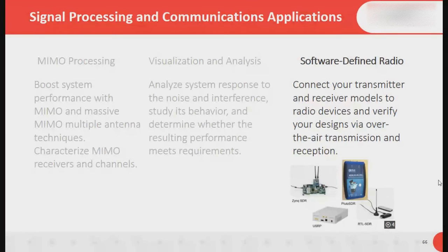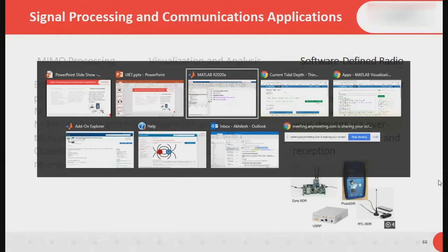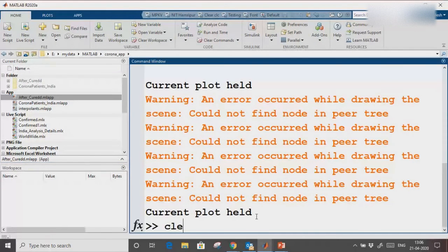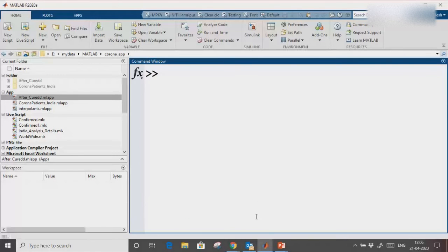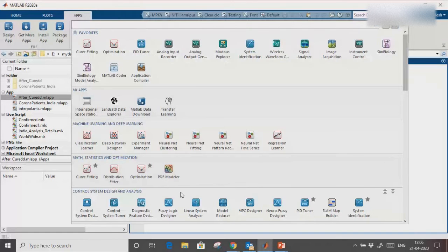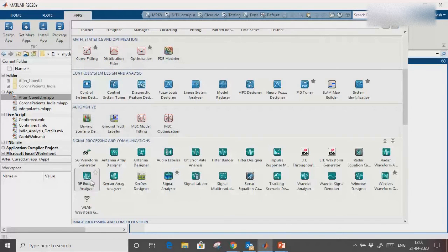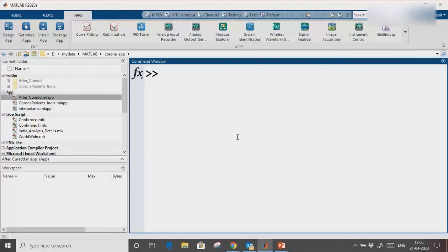In MATLAB, sir, when you design the antenna, let me show you, the antenna designer. Antenna designing is in the Antenna Toolbox, sir. The app group is signal processing, but it is in the Antenna Toolbox. So here you can design your antenna using this app. Then further, you can generate a Gerber file of that antenna. Only for the antenna.